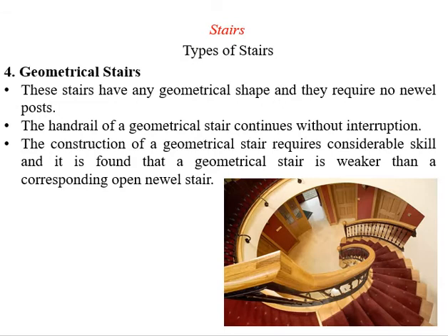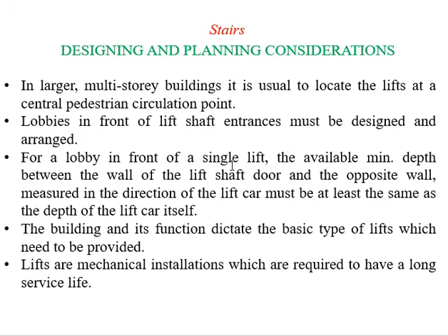Again, we can have a geometrical type of structure, helical type of structure of stairs, which have various shapes and sizes, and they require no newel post at the intermediate points. Again, the handrails of these geometrical stairs, these are the handrails. They are continuous and they are not broken at any point, and we have provided a rail over here. These are simply continuous and smooth. But from the structural point of view, they are weaker in comparison with the other newel type of stairs. Okay, so next and last slide is about the planning and the designing of the stairs.